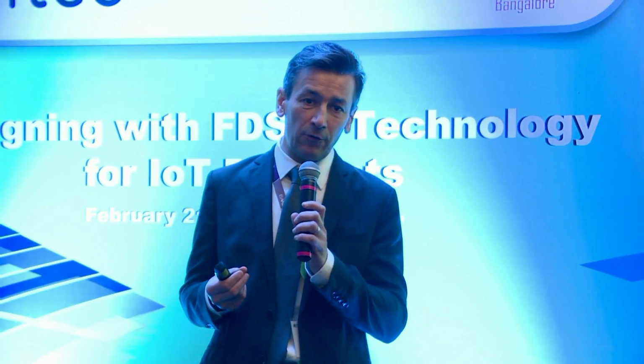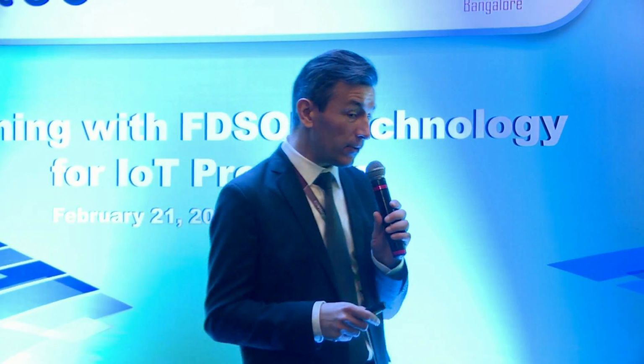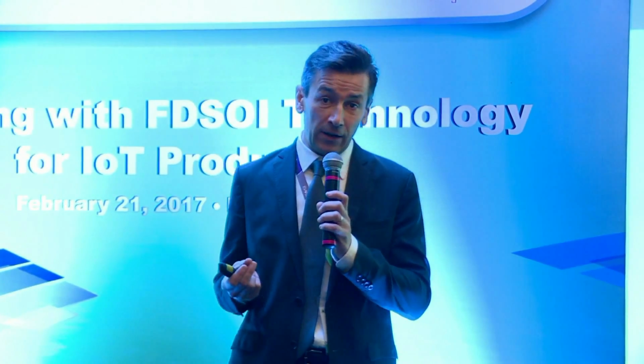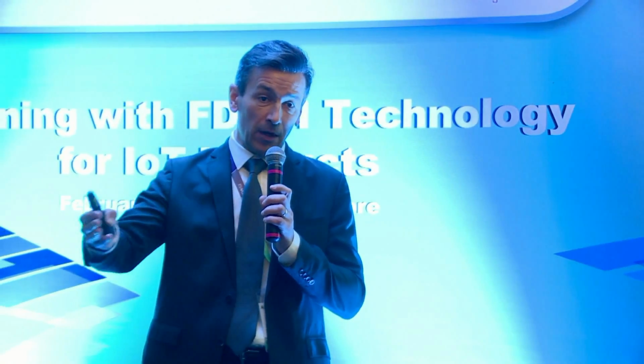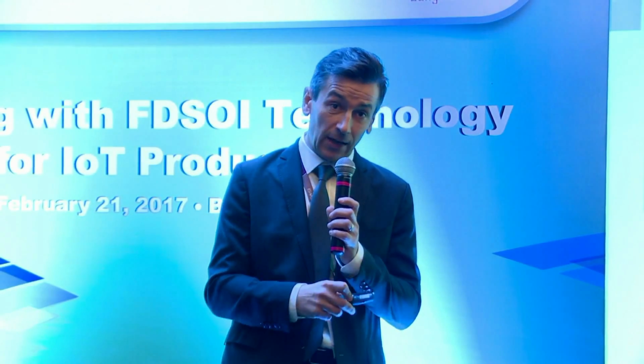So just first, a list of the key things which are unique for FDSOI, and I will go after that to probably one slide for each as an example. So first one, body bias. Paul mentioned body bias. With FDSOI, and only with FDSOI, you can design your chip in a way that, at software level, you can use the same transistor either at very low leakage or very high performance, and you can move it from one state to another depending on what application and function you're using. Think about mobile applications. Think about IoT. It's just a perfect feature for this type of application. I'll come back to this.